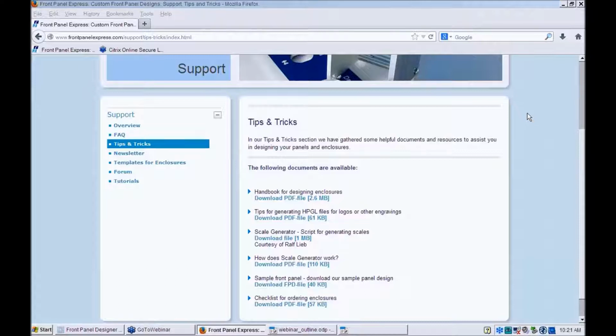Only 4 screws for the front and back held it together. Is there a better way to do this? Yes, in the manual, there is a housing bracket. You can place this in support throughout your front and back panels to give it the support between the profiles. This is also the example that Chad expressed with the side profile front panel, that you may put the grooves in the front so you don't have the countersinks on the front of your panel that you're trying to display.